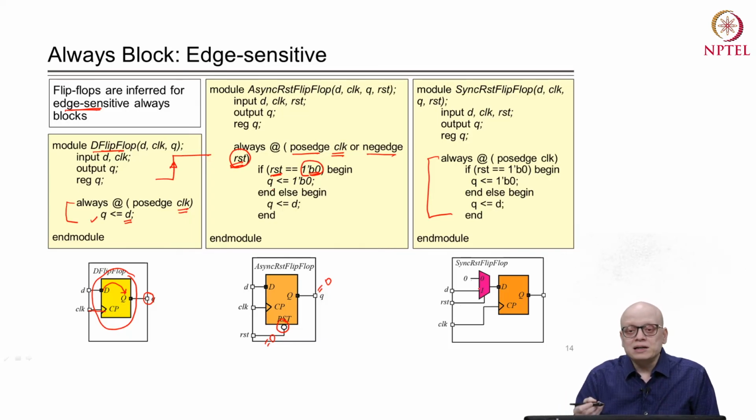So, instead of say a multiplexer, the tool can always instantiate an AND and OR gate, and so the exact implementation of the RTL construct is dependent on the tool, right. For a given Boolean function, the tool can implement it in many different kinds of ways, but based on the meaning of the Verilog construct, the tool will always generate a circuit which is functionally equivalent to what we are discussing in this lecture.